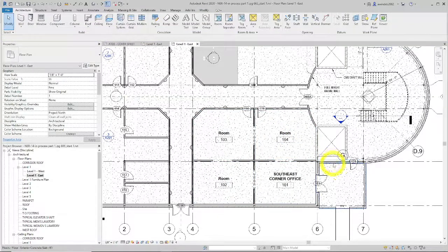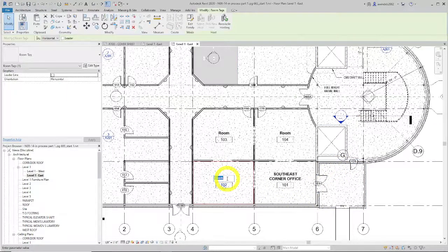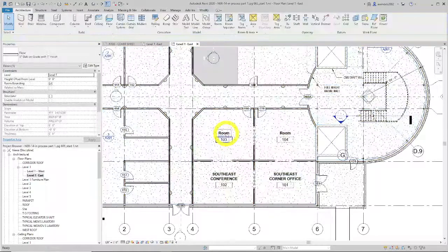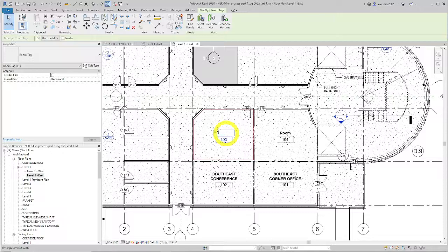And just for the sake of moving on here a little bit, we'll rename a couple of these right now. I like the order they're in already, so we'll leave that alone, but you can always go in and change that. Keep in mind, you can't have two of the same room numbers, so you might have to get creative in how you renumber one, maybe a higher number before you cascade back down. So keep that in mind. You can't have duplicates in rooms.